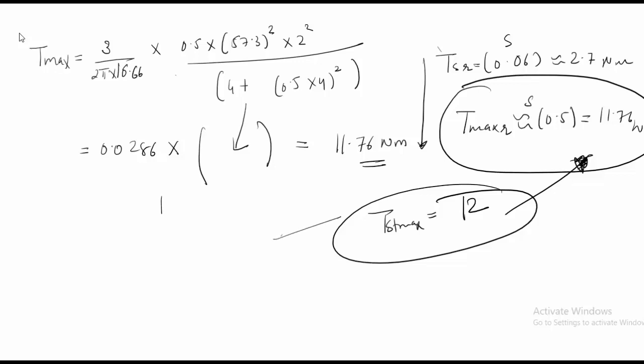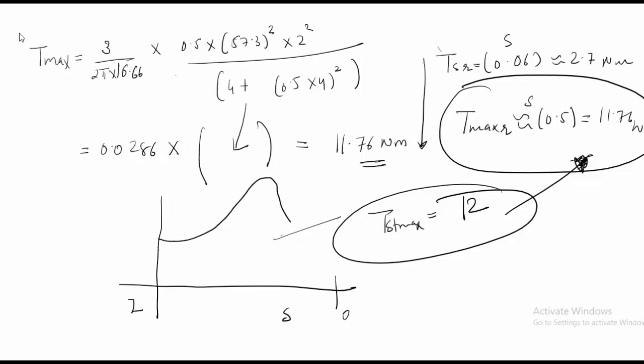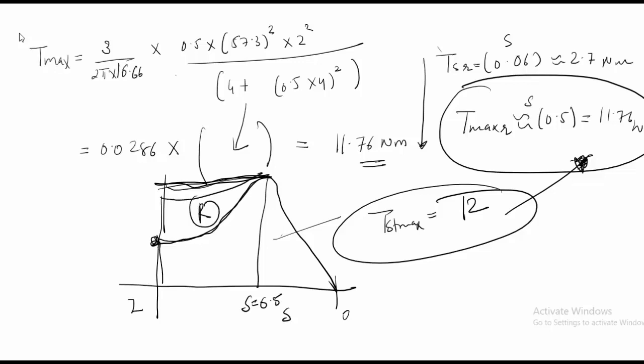Again, if you see the torque-slip curve, if this is your slip of 0 and this is a slip of 1, then it is possible to have a curve something like this, where you will have a maximum torque at the slip of 0.5. Beyond this, if you try to run this machine, it is called the pull out torque, and this is your starting torque at a specific resistance. So it is possible to increase this by increasing your resistance. If you are increasing it to 2 times, then it's possible to increase whatever torque you are getting here.